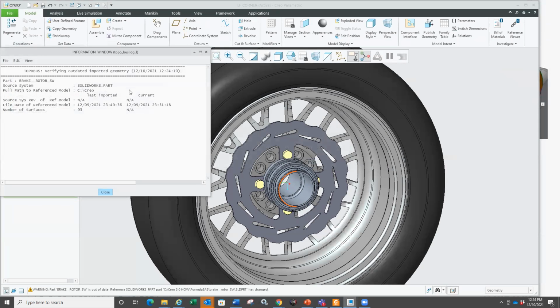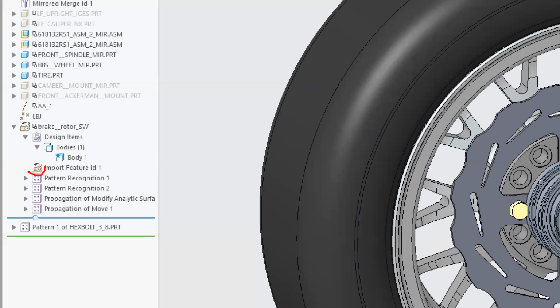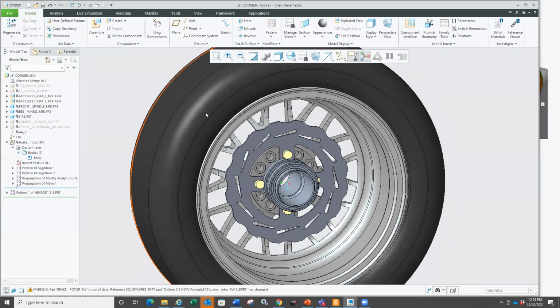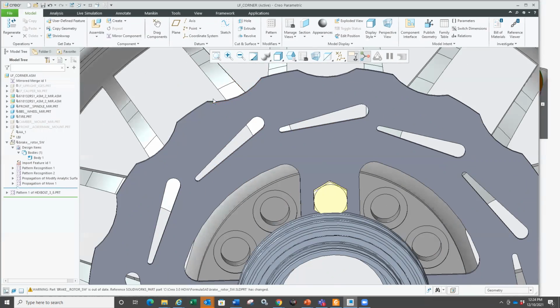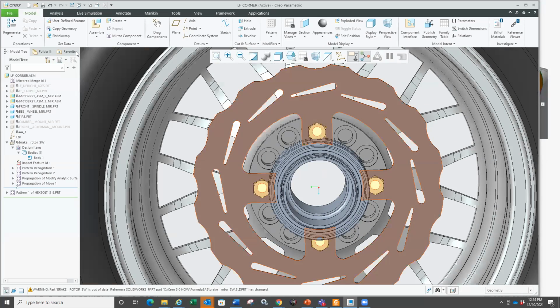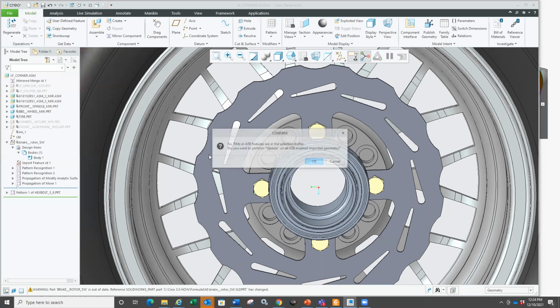and it's going to run through the entire assembly, and it's telling me, okay, yeah, there is a change. I do see a different one in the folder or in my workspace compared to what you have in session for the SolidWorks file. It also gives you a little outdated symbol, if you can notice here, a little clock symbol next to the import feature. I just created another SolidWorks file without the cuts on the rim on the outside, right? That's all it is. So I'm going to go to the ATB and update that.